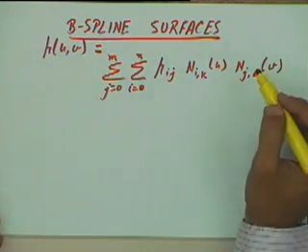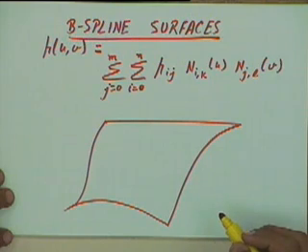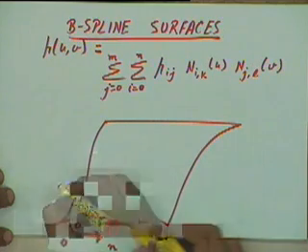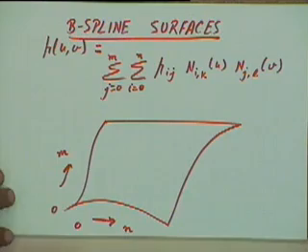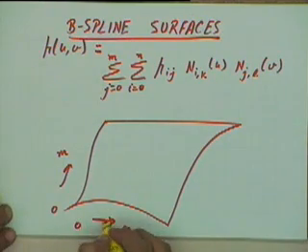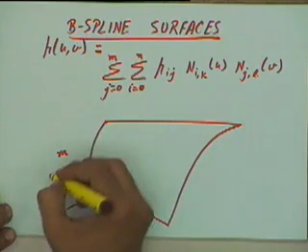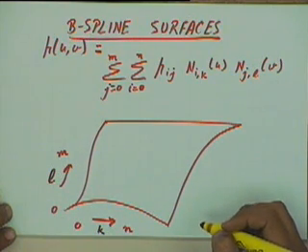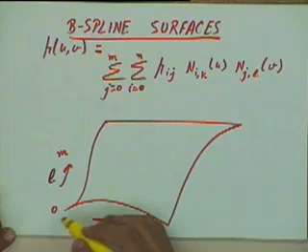Just as we have defined B-spline curves, now if this is a general surface that we want to define, we have a number of points in this direction going from 0 to n, the number of points in this direction going from 0 to m, and in addition to that we define the degree of this curve in this direction as k and the degree in this direction as L. So this k and this L will control the degree of local control in the two directions.